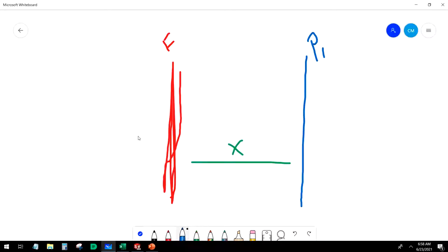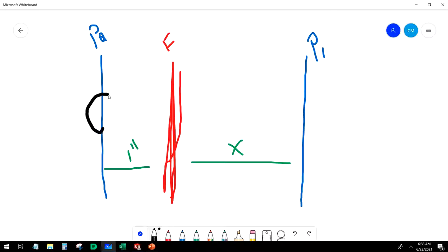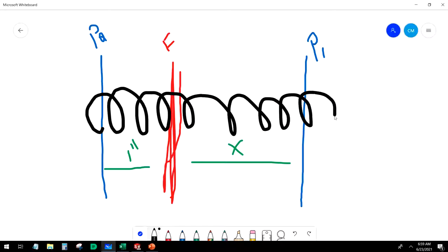We're then going to create another plane to this side. This will be plane 2. This distance will only be about an inch or so. Now the reason why we have to create these two planes is because we're going to take a helix and wrap it around like this. We're then going to have a circle follow the path of that helix. We're going to use the swept boss base feature to do that.